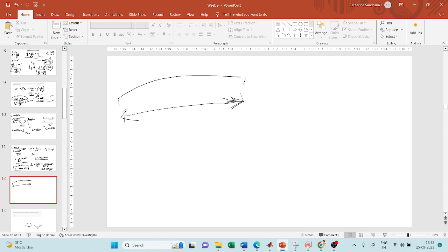No, it is not a horizontal distance because your vehicle will be traveling on the curve. So SSD is calculated along the length of the curve. Only then you will be able to stop, right? You cannot take a projection of that. Whereas for vertical curves, length is always the projection of the vertical curve.